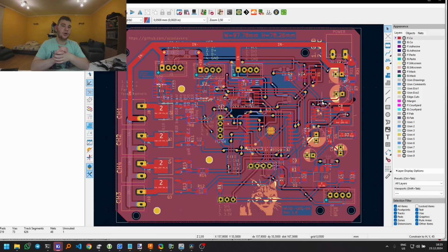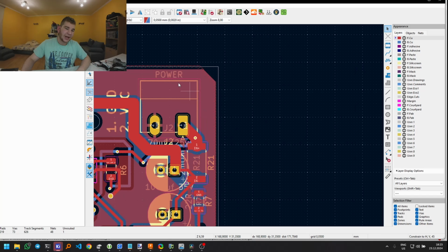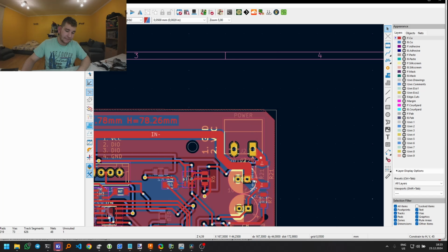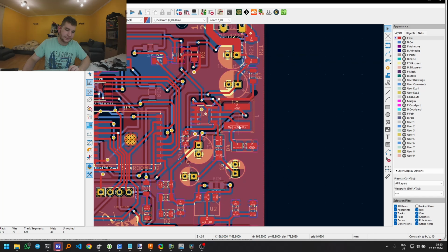Let's quickly talk about our final prototype design, the PCB, and some schematic decisions. First we have a connector, capacitors, and a shunt, because we have an INA219 chip, which will be measuring current and voltage on the controller without being consumed. So it's important to have this shunt.